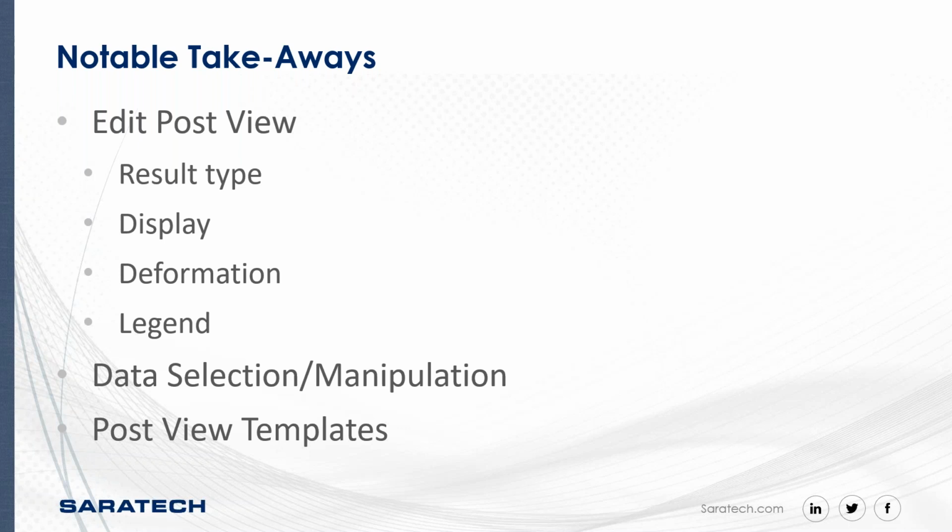And some notable takeaways from that is really for display purposes, that edit post view command, where you can change your result type, the display, the deformation, you can adjust your legend, and you can also, very important, you can save a template of whatever result display you create.